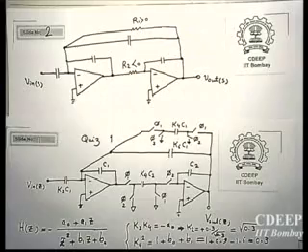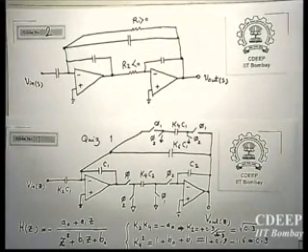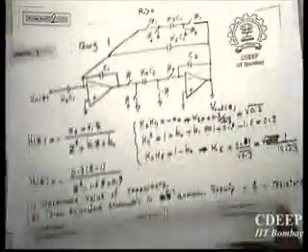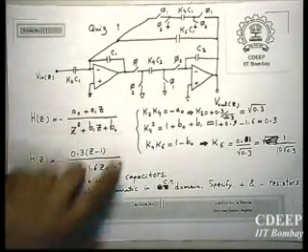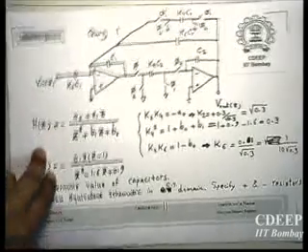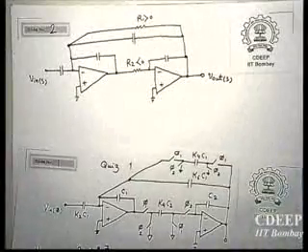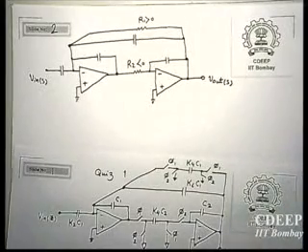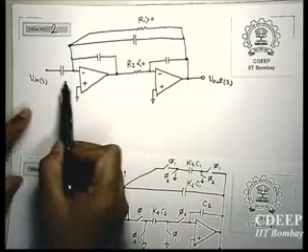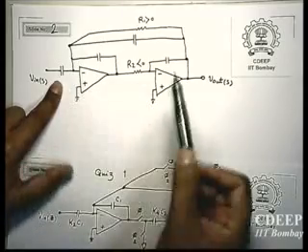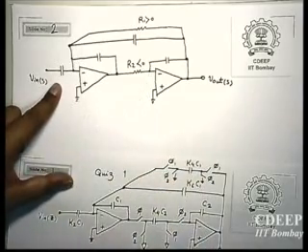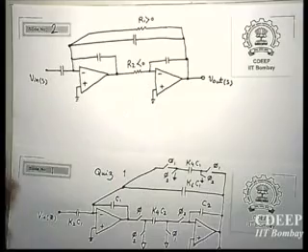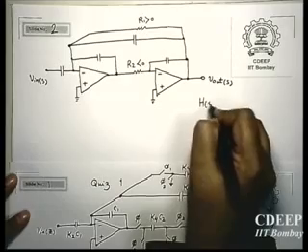So if you remember, once I asked you, what is the use of having the forward Euler approximation? It is to implement a negative resistor. So two things have been removed. One resistor which was parallel to this capacitor and one capacitor which was between this node and the input node. These two create two zeros. Those two zeros have been removed. Therefore, here your H(S) also will be something like this.